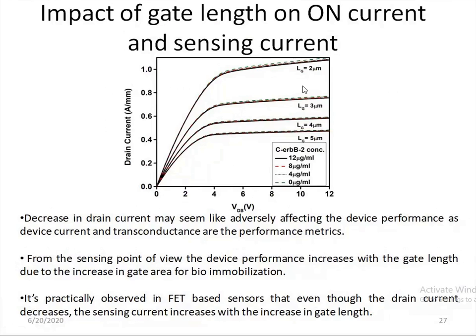If we are going for a high power domain or a high frequency domain, people focus on scaling down or miniaturization. They have to follow different roadmaps like ITRS roadmaps, and they have to get very high currents, very high frequencies, etc. But in our case, being a sensing domain person, I don't focus on miniaturization. I focus on enhancing the sensitivity of the device. For enhancing the sensitivity, we can't go for miniaturization, or for using minimum gate length, because as I said, it is on the gate that we introduce the biomolecules. If we have to introduce something on a gate, we need a larger area of the gate so that a larger amount of molecules can be introduced and the sensing can be done at a very good level.